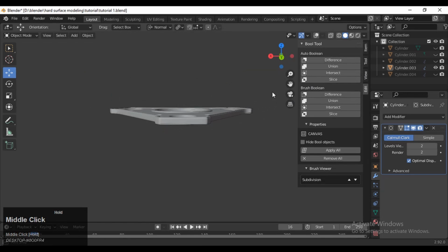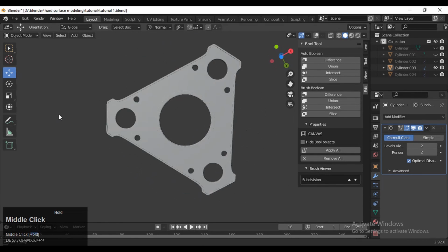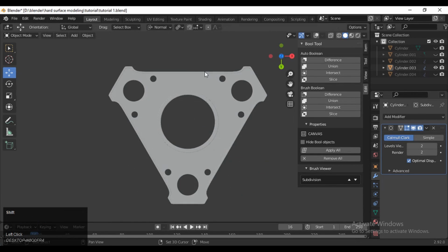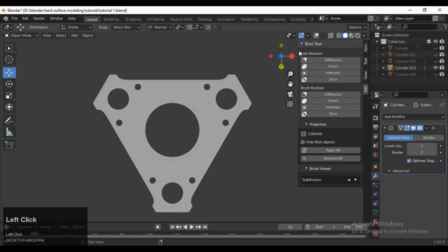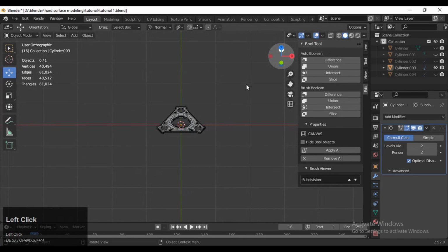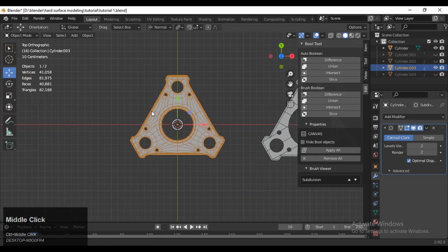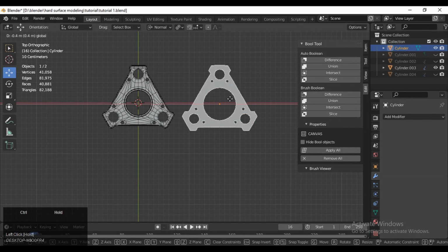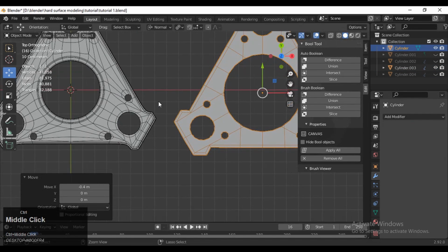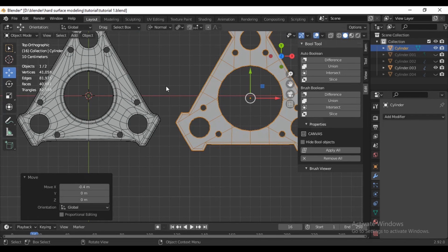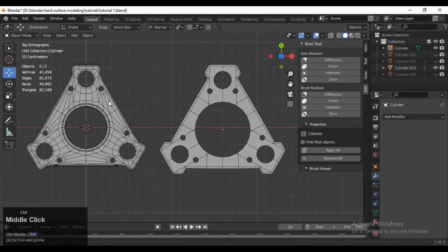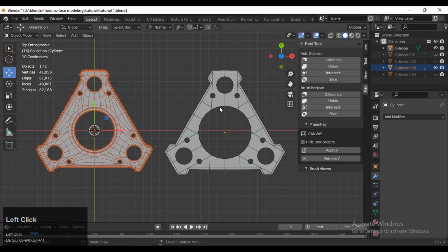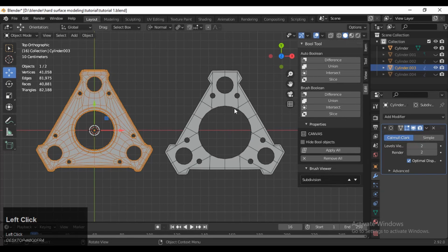And if you compare both, then you can understand the topological difference there. One is with the right topology with the subd modeling methods, another is a weird topology with the n-gon. This kind of n-gon topology is fine for games, but not for VFX production.